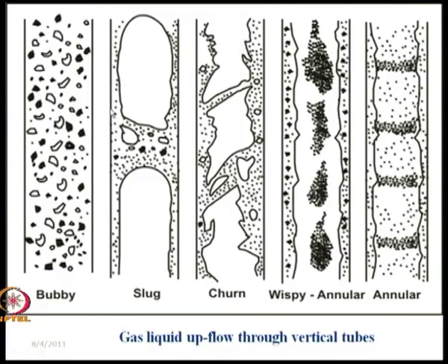In this case there are a number of interesting things. Firstly, there is periodic flow phenomena. Secondly, if you observe slug flow, you will find regions where the liquid is flowing downwards and regions where the liquid is flowing upward. So, if you notice the wall shear stress, it keeps changing direction with the passage of the bubble and the liquid slug.